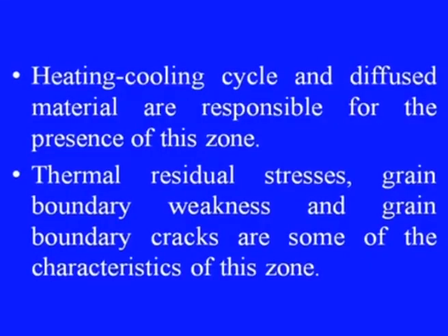Of course, it can vary depending on the parameters we use, the material we use, and basically the pressure at which we are using the dielectric to flow, or the flow rate of the dielectric. The heating cooling cycle and diffused material are responsible for the presence of this zone.